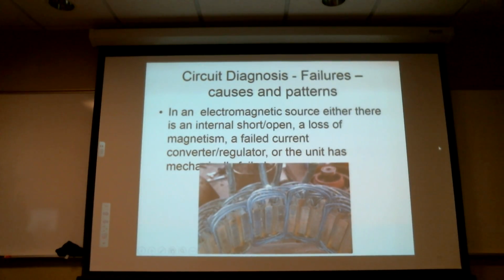Simple solution is take a long, thin screwdriver, or a long stiff piece of tube, set it up against the housing of the bearing, and push it up against your ear. Not enough to damage your ear, but kind of up there. It'll transmit right through the tube and into your head. You'll hear it. When you get near the bearing, it gets real loud. Touch somewhere further away, it gets quiet. You can very quickly identify it.